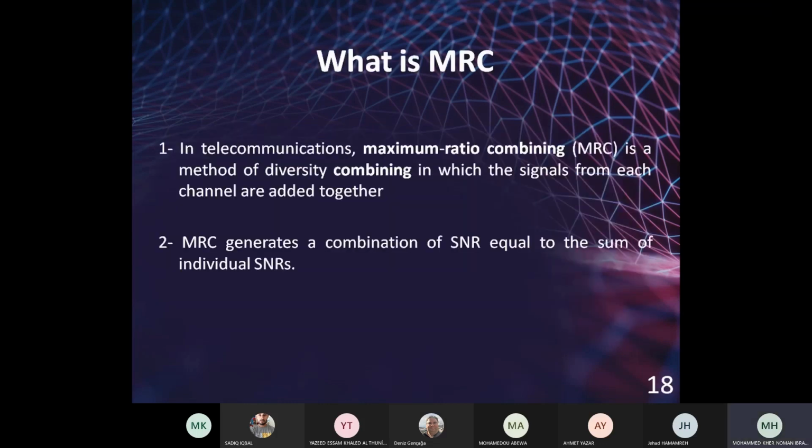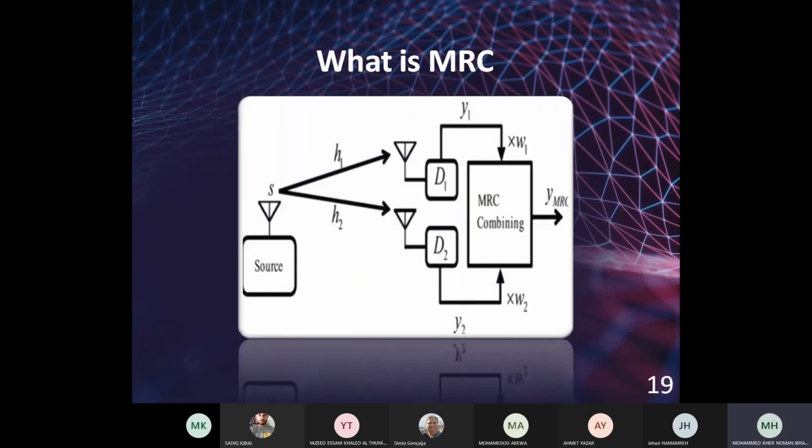Before showing my results, I want to speak a little about maximum ratio combining. I will also compare my results that came from SSD with the MRC and also the conventional OFDM model. For the MRC system model, I used 2 antennas to receive the same signals from the 2 channels and combined these signals using their weights in the MRC combiner. Note that this will happen after removing the cyclic prefix and the FFT process.